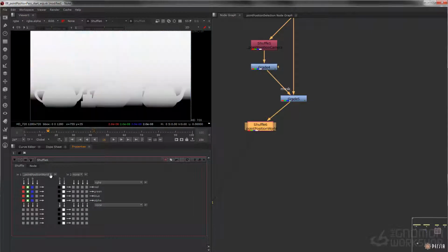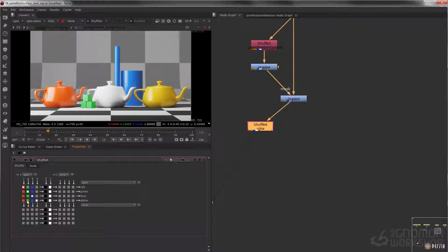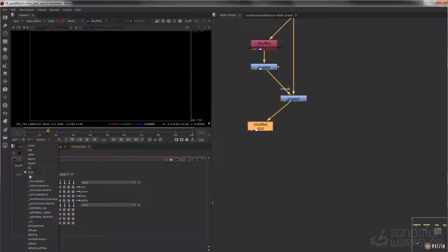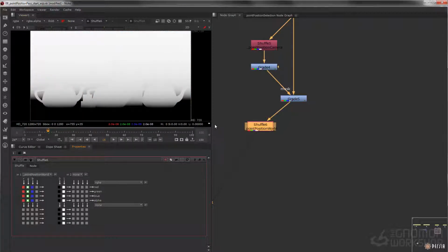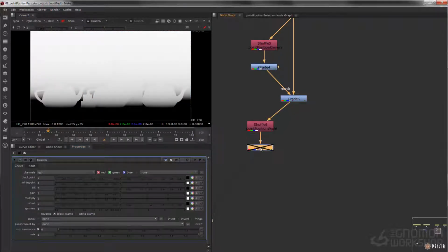So if I select green for the Y channel into all those nodes, I can drop in another grade node and disable that, and then I can color pick my black and white point, which will remap our image.